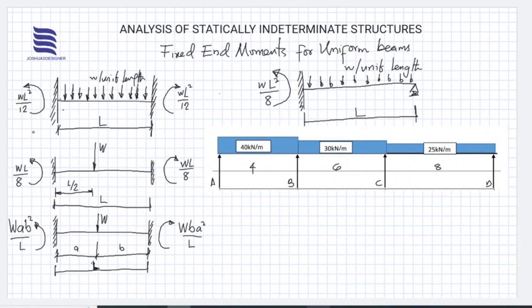So now next to find is the fixed end moments, right? So these are the fixed end moments for uniform beams, and I have about 4 of them here, as applied to your beam analysis. You might want to search for some others so that you can have the right fixed end moment values for your application, right? So to obtain that straightforward, let's just go through, and you have to be mindful of the uniqueness of each member span, then apply the value appropriately.